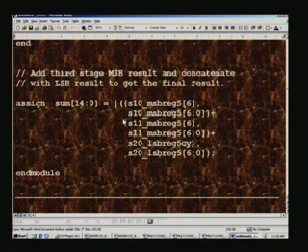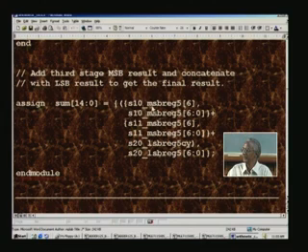So the final result is addition of two numbers that results from the output of the second stage, and that is basically S10 and S11, and we had to sign extend as we had done before, and that is what we had done here. The very same thing is extended here, and to that we have to add the MSB, because we have not done the addition as yet, we have done addition only for LSB, and having done that one, we also have to concatenate the LSB because we have added this in the previous stages, and that LSB will have to be concatenated.